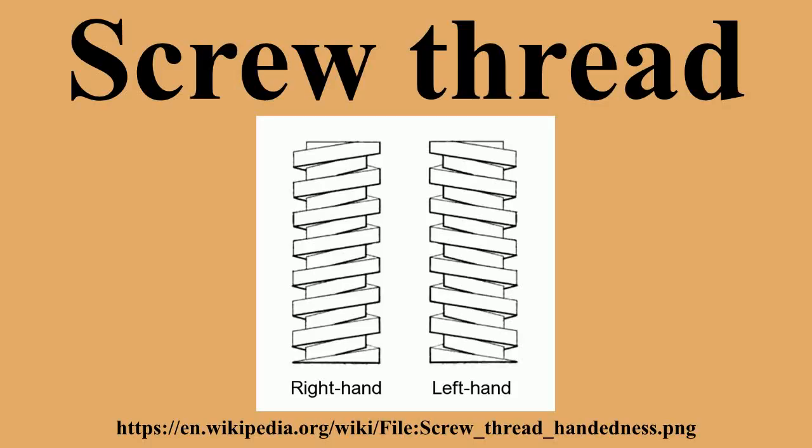Thread depth. Screw threads are almost never made perfectly sharp, but instead are truncated, yielding a final thread depth that can be expressed as a fraction of the pitch value. The UTS and ISO standards codify the amount of truncation, including tolerance ranges. A perfectly sharp 60 degree V thread will have a depth of thread equal to .866 of the pitch. This fact is intrinsic to the geometry of an equilateral triangle, a direct result of the basic trigonometric functions. It is independent of measurement units.